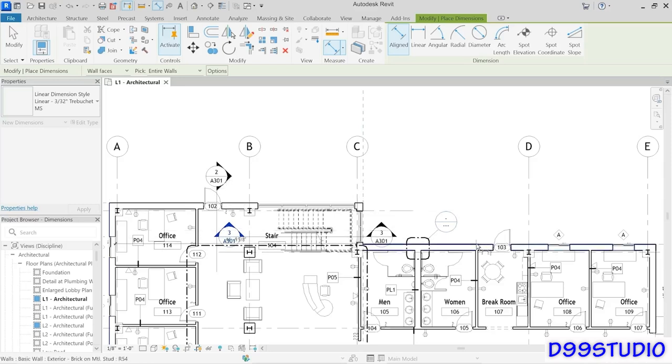But if I come over to this wall and click it, it will add that wall to the selection. And it's not necessary to hold any modifier keys down. So it will just highlight that wall and let you click it. So just like when you're in individual references mode, you're able to select multiple references. The same is true when you're in the entire walls option.